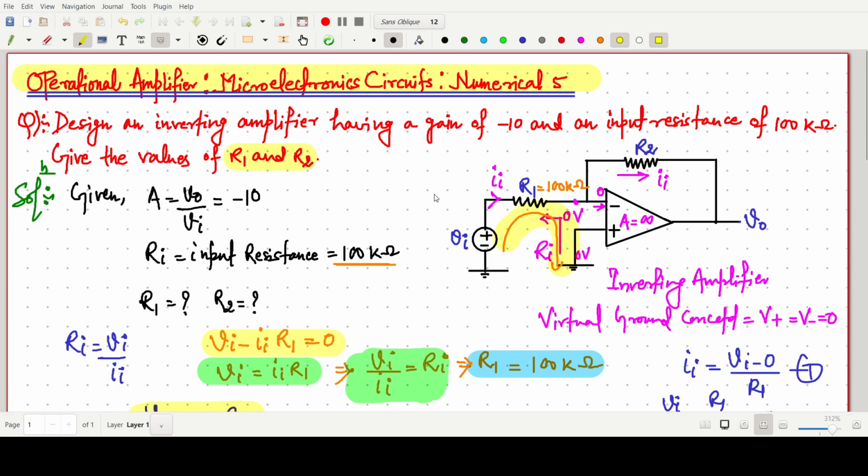Finally, R2 is 1 mega ohm and R1 is 100 kilo ohm for gain minus 10. So this is all about this question. Thank you for watching this video.